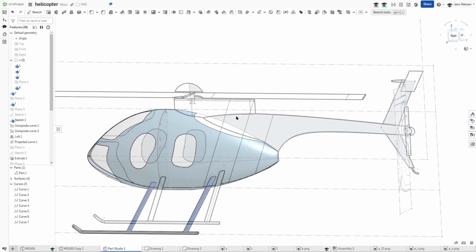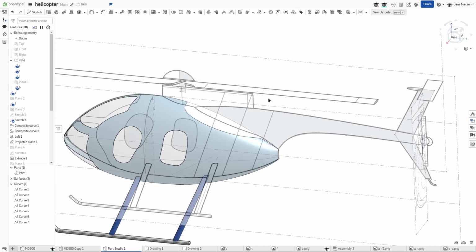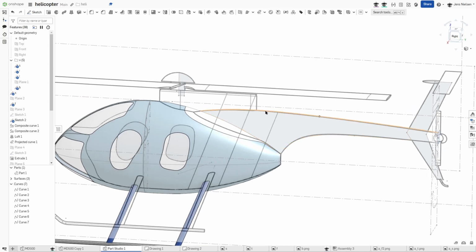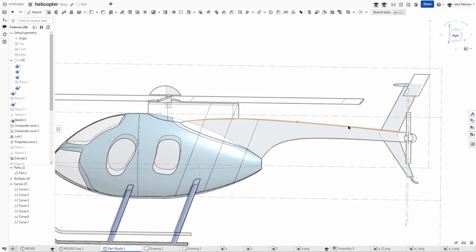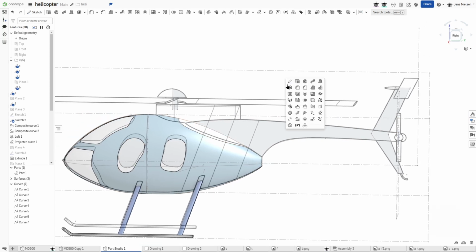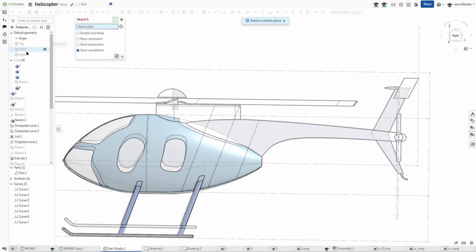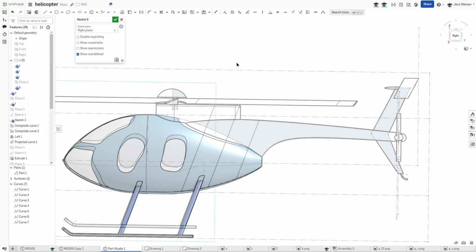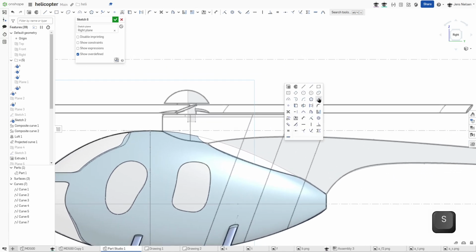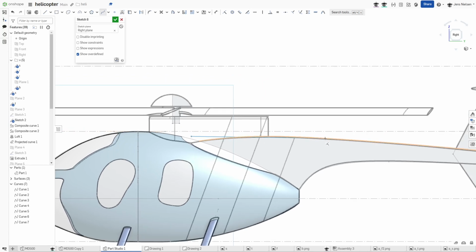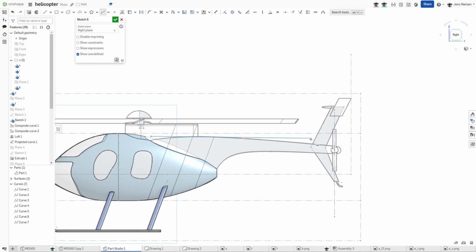I drew from that side image, but that main rotor case here falsifies the position of that line. So I need a new line up to that point here. And I will just create that with the spline from here to over there.